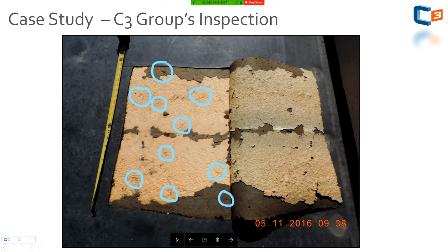And then this is showing the picture we showed you earlier of ISO in an adhered system, but I'm circling the areas that I identified prior to cutting. This was actually beneficial because part of the facer was intact and part of it pulled off with the membrane. So you can see the lower right hit there. You can see the facer fracture, and then you go where there's no facer and it pulled off with the membrane, and you can see depressions and the same thing.